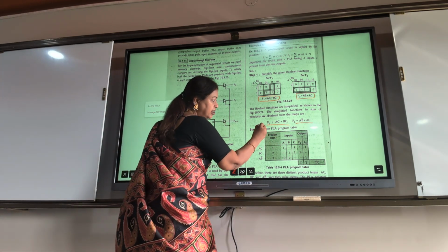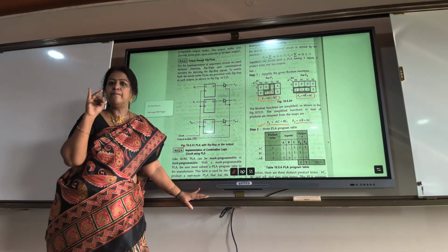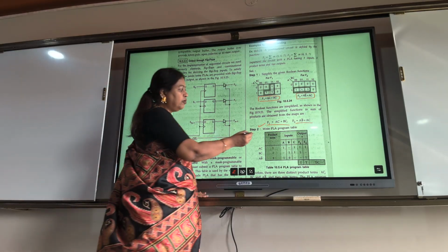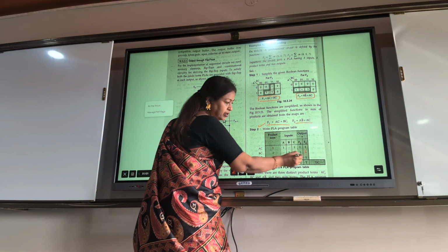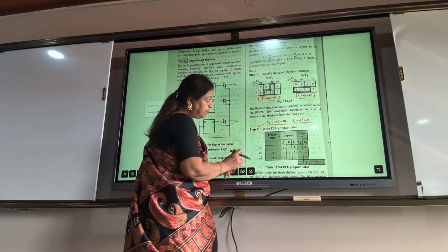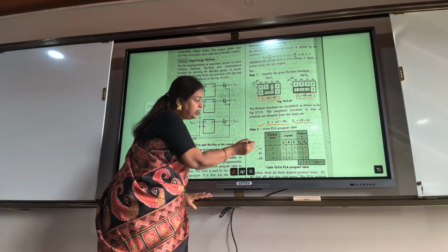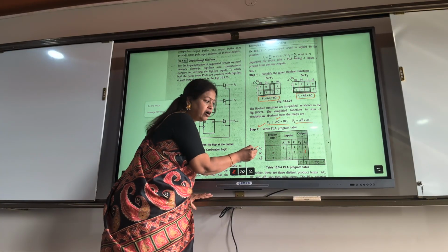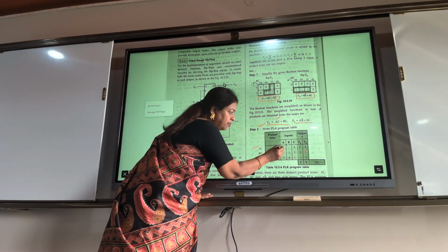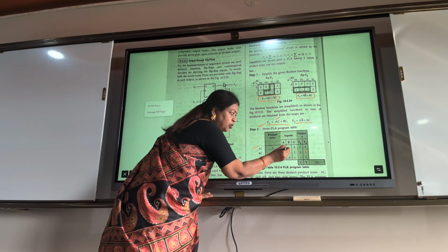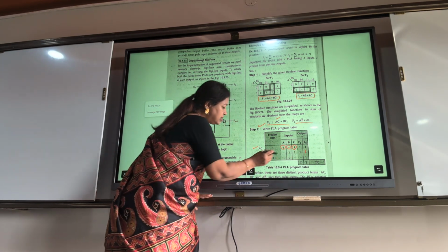Next, this is what is called the PLA program table. So we have to program both AND and OR. So I am going to put how many product terms are there and what about the OR terms. So what about the product terms? I have AC. AC means A is in normal form, C is in normal form, and I don't have B here. So A in normal form I put as 1. There is no B term, so I am putting a dash, and there is a C term.